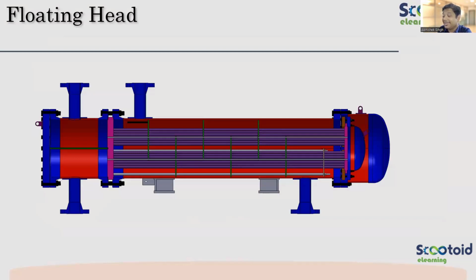So you need 3 alphabets, Mohammed. I'm not talking about only the rear end. Complete heat exchanger nomenclature with 3 letters. Front, then shell type, then the rear end. Monica is saying BED. D we never discussed. There is no D type in rear end.